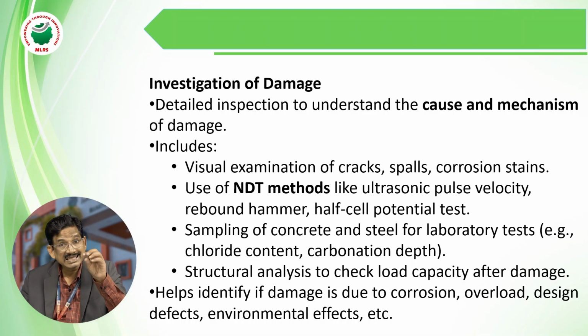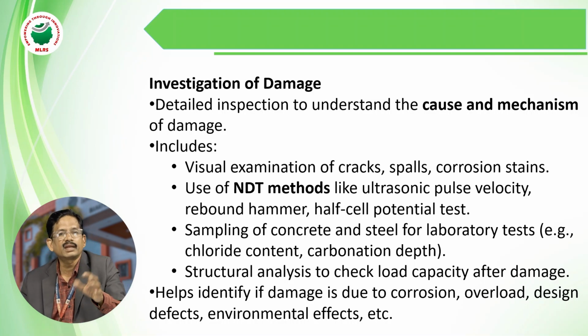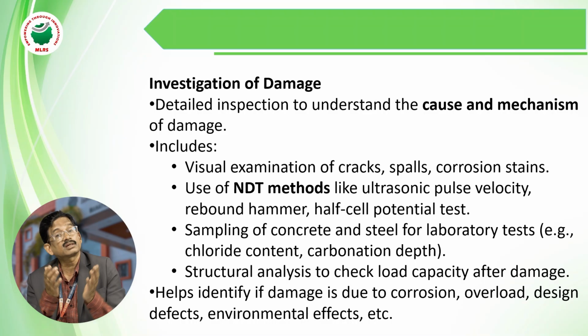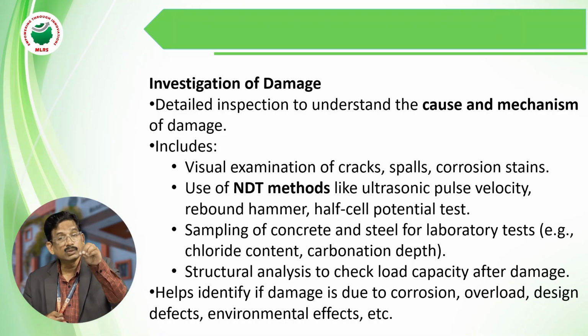So how much it resists the chloride content has to be tested in the laboratory with the help of the rapid chloride permeability tester. Next, the carbonation test. With the help of the carbonation test, we have to test how much carbonation it has.